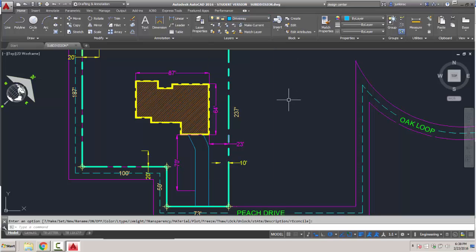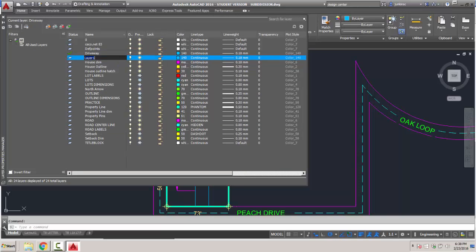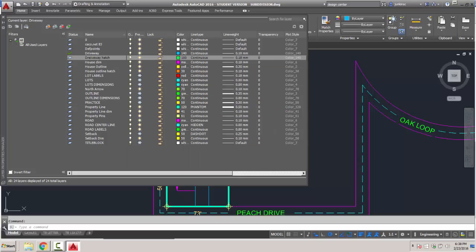So this driveway is going to be hatched with a, they use a herringbone. Now it's a walkway they got around there. So hatch is going to be, yep, H-bone on page 614. So let's create a layer called, new layer. It's going to be driveway hatch. And we'll give it a different color.